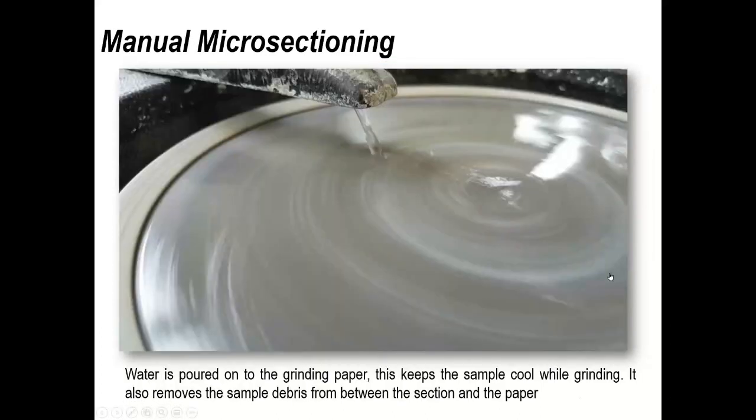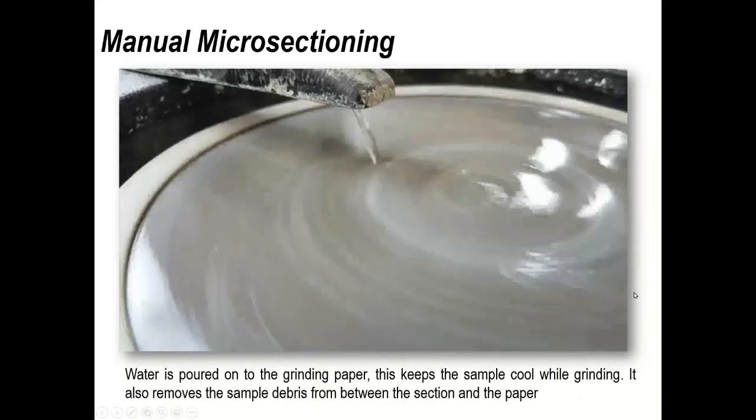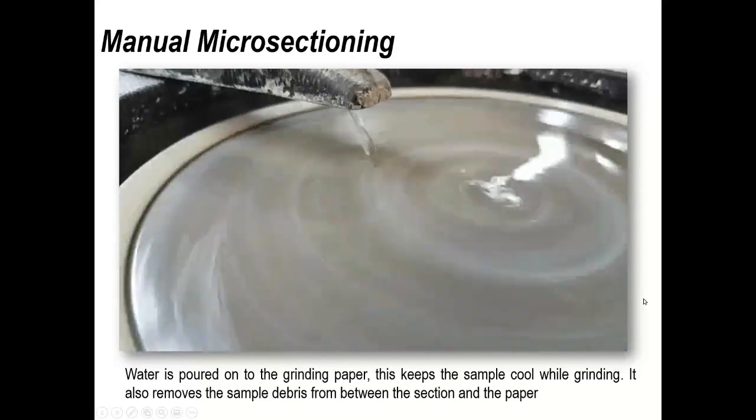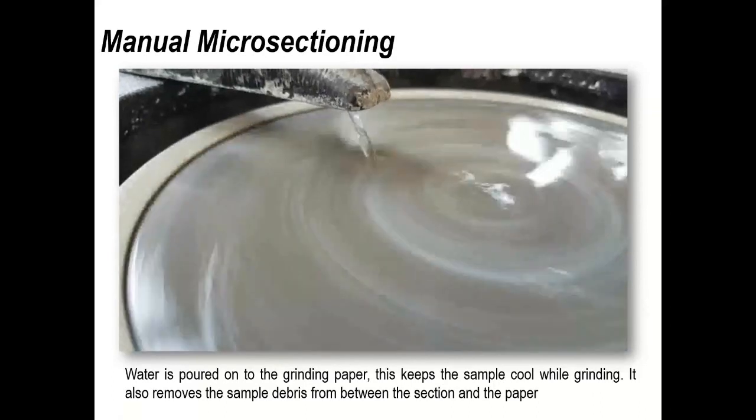So again, the actual amount of water you're applying, this is just in a grinding operation. It's very dependent on what you're removing, but really it's not much more than a dribble, but it's doing those two things. It's removing the debris, and again, it's maintaining the temperature of the sample. If you try and grind without any water, lubricant, then you're going to feel the temperature rise quite quickly.